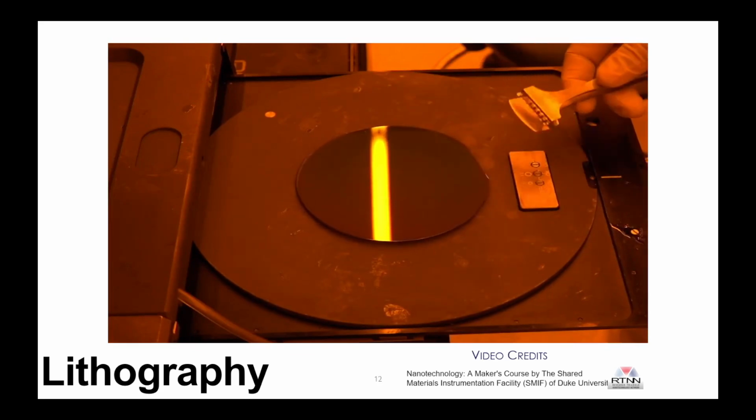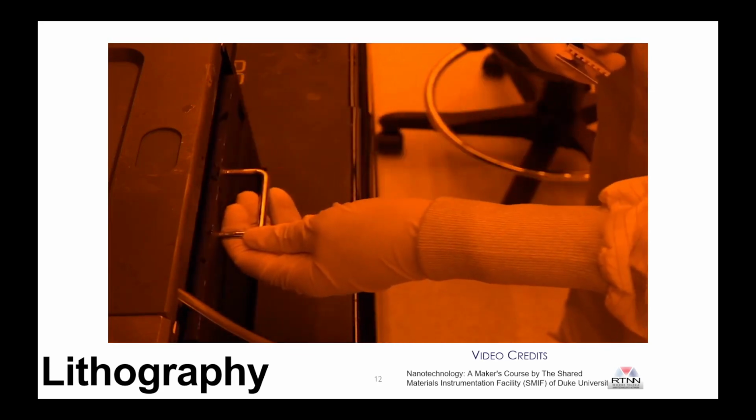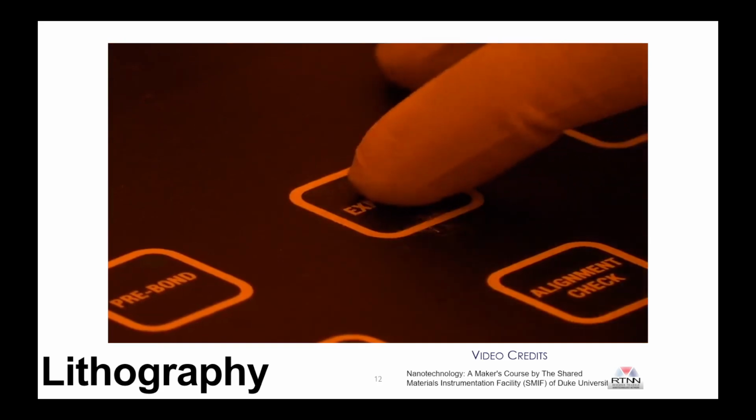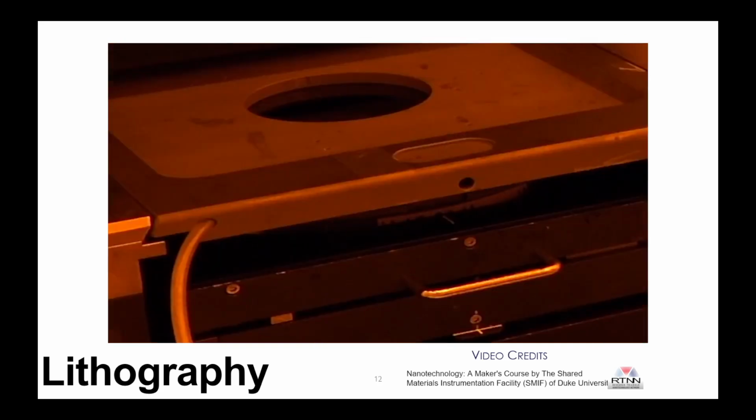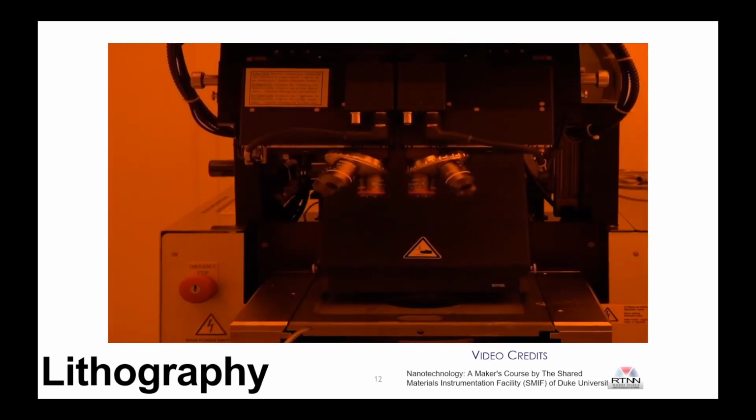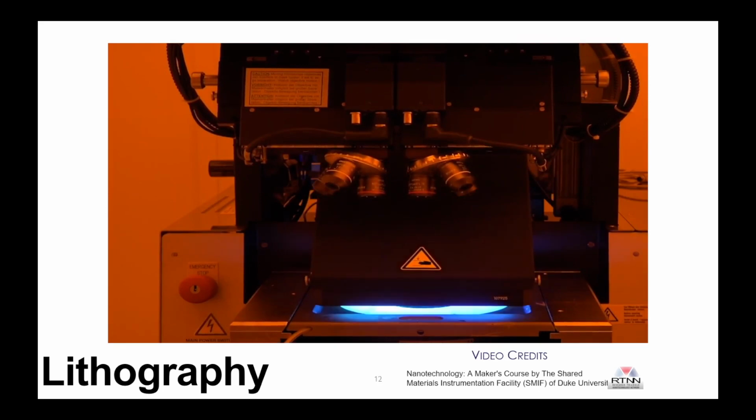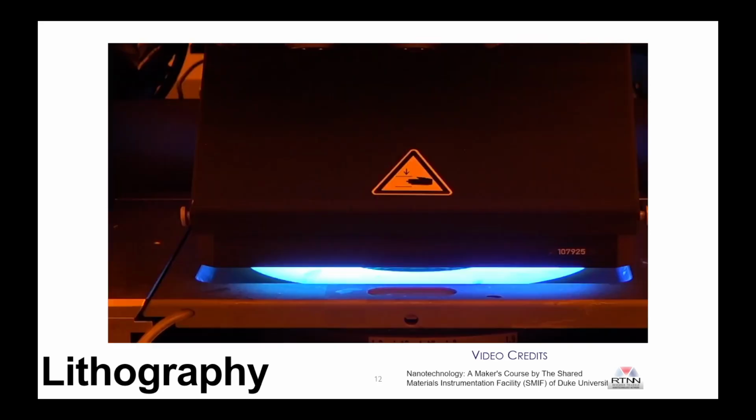They have to put the wafer here on the sample holder in the photolithography machine. Now they have to expose it to UV light. You can see the lamp holder will come to the front. Now the exposing of the pattern will take place with UV light.